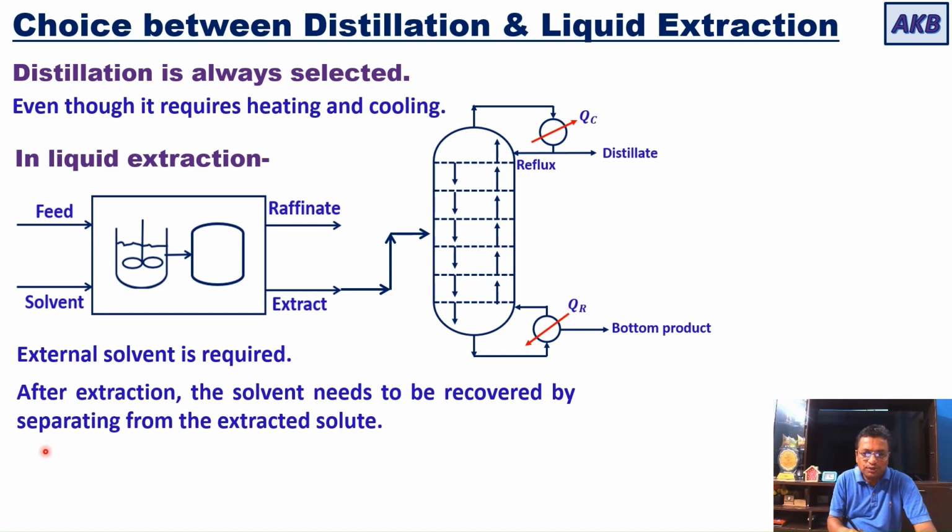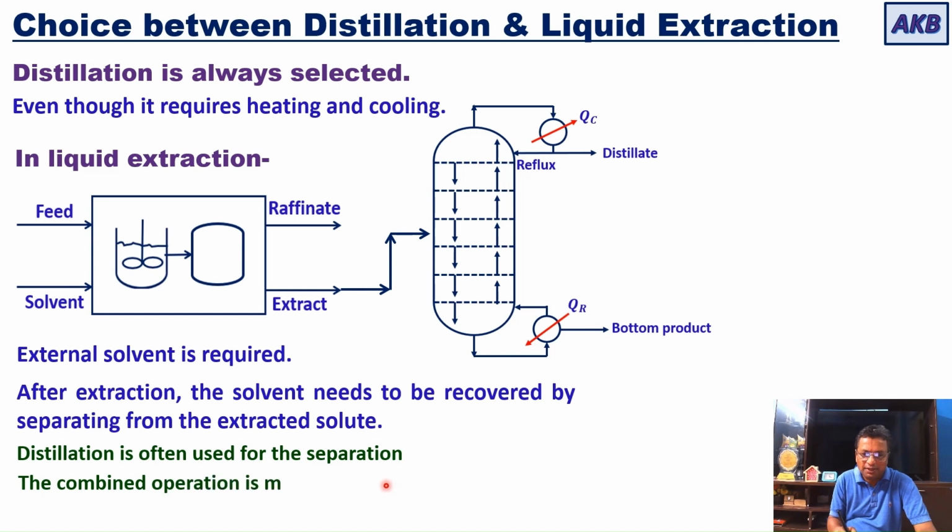How are you going to do that? By separating from the extracted solute, and distillation is often used for this separation. And that means in liquid extraction, we need to use two operations. There is a combination of extraction and distillation. And this combined operation is more complicated, and most of the time it is more expensive than distillation.